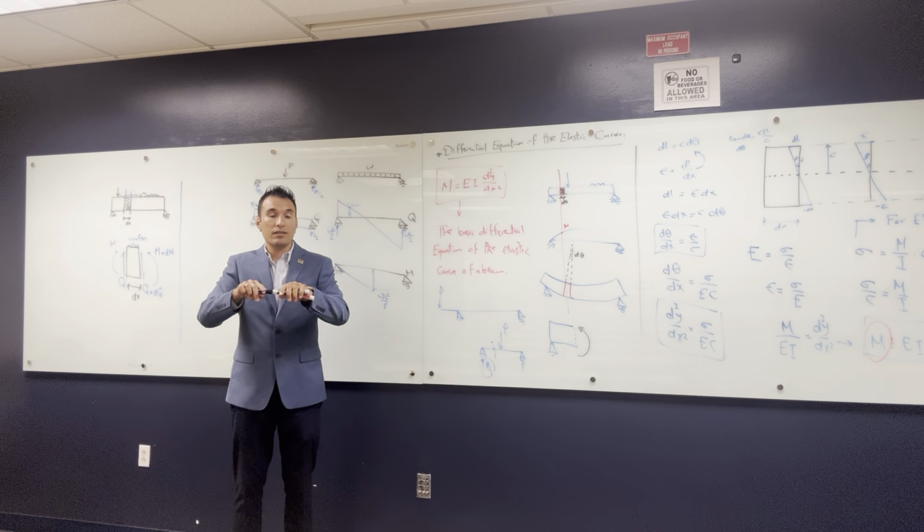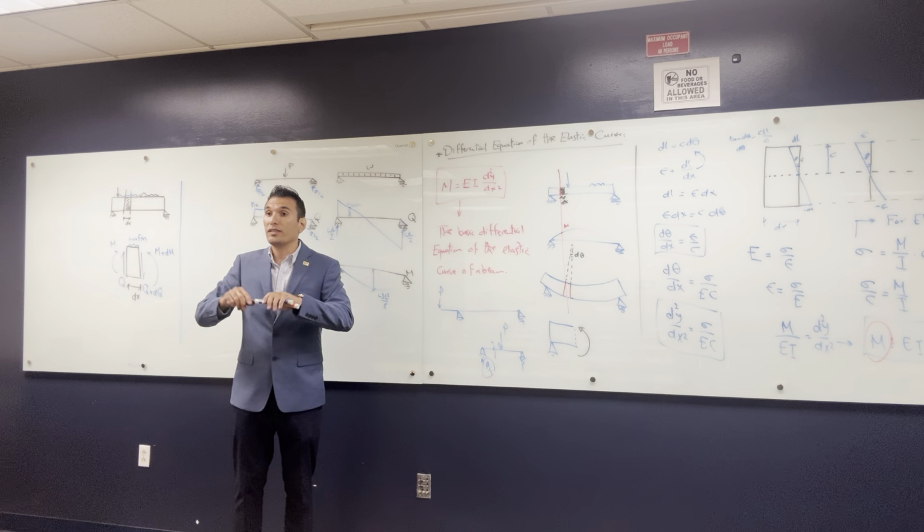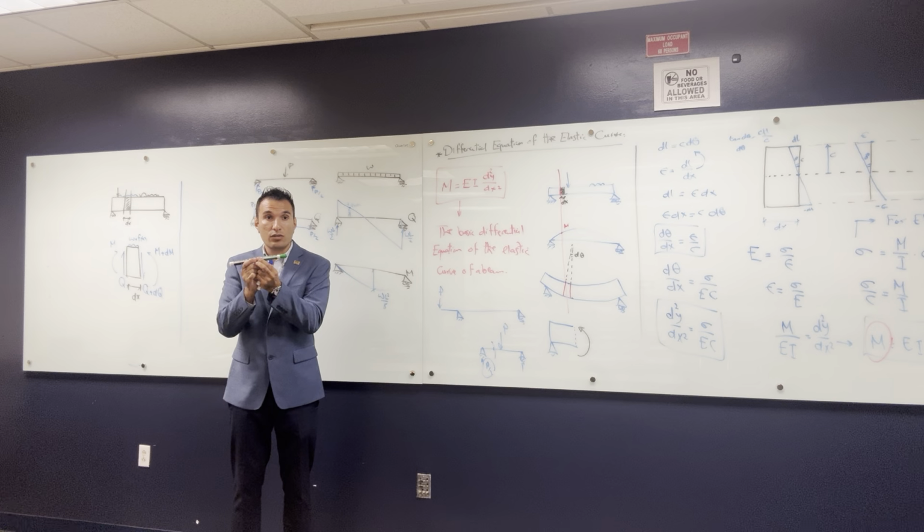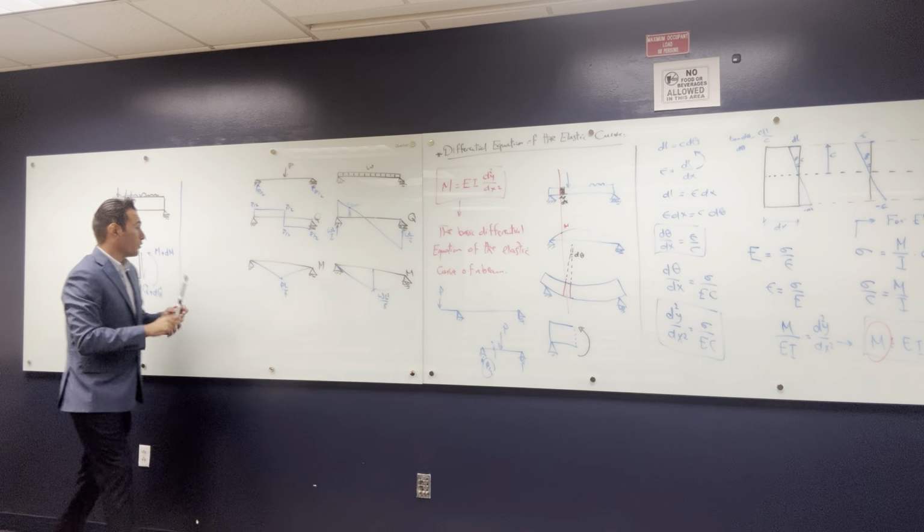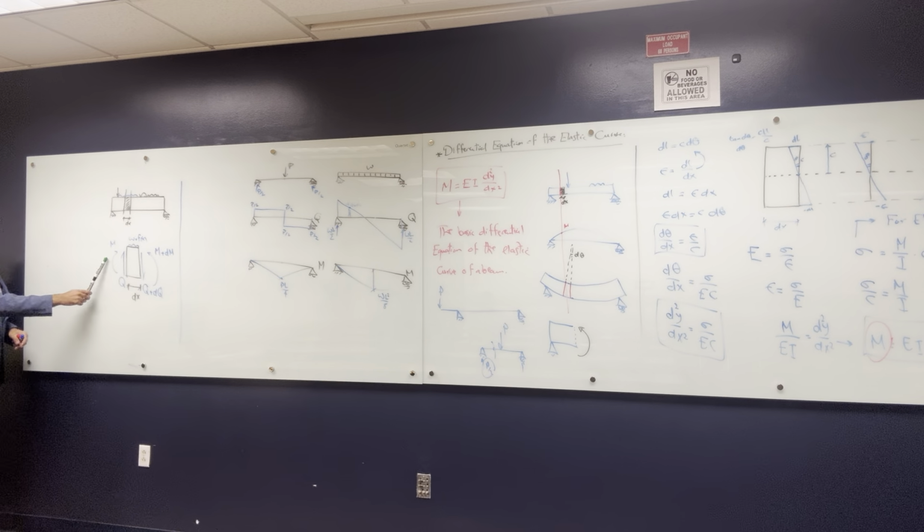So definitely this section is not going to be stable. So assuming that this is a stable structure, if we take this cross section out, the internal forces on the left and the right stabilize each other. So we can say that sum Fy for this small section, let's assume that positive is up, is equal to 0. So all the loads up and down are stabilizing each other.